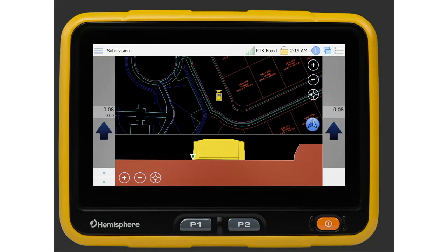This option will be used if the project has been designed by an engineer and the job has a set of blueprints or plans. These plans will be based off a known horizontal and vertical grid that the machine will have to match. I have an example of a job loaded and shown here. Notice all of the grade breaks shown on the side of the road in the cross-section view. This is showing you an image of a dozer blade as you're looking at it from the cab.